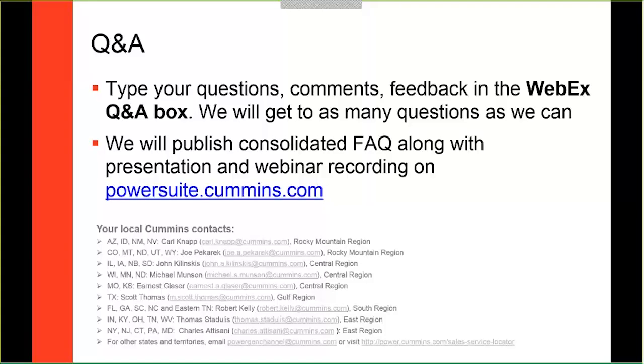Awesome. Next question. What changes are made to a generator set in order to make it rated fully single-phase output? Good question. So typically what we see many generator set manufacturers do in order to achieve a full output on the generator set in a single-phase configuration is typically an oversized alternator in order to accommodate the single-phase loads.